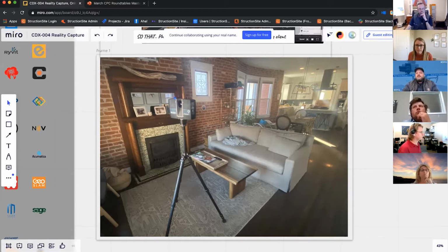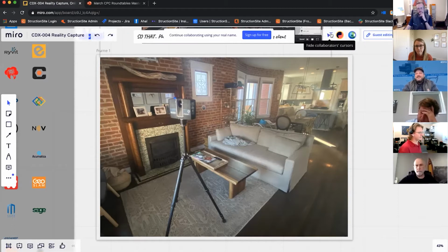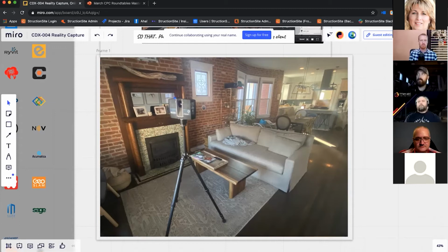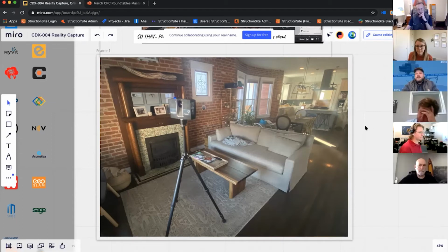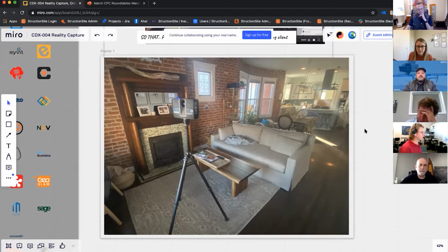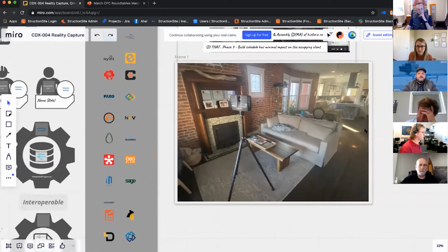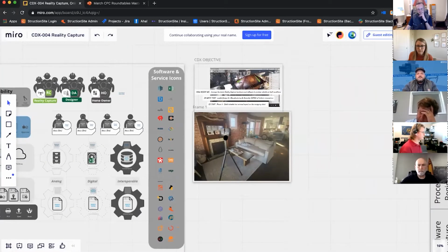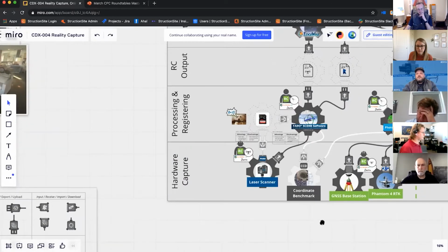The nice thing with this is that it's a more accurate as-built than just taking a tape measure to things. Obviously, these walls are not plumb, and there's a lot of interesting structural work that's happened over the years, and with the millimeter accuracy of the laser scanning, we're going to be able to document that and hand it over to the architect. So this is the first level of his house, and I think what we should do is just walk through.